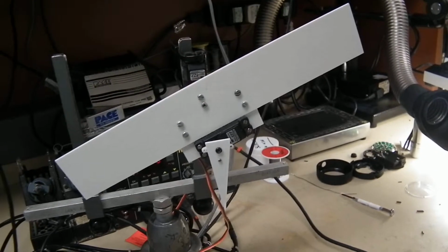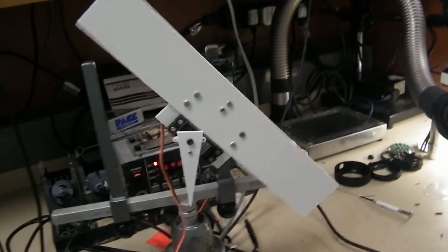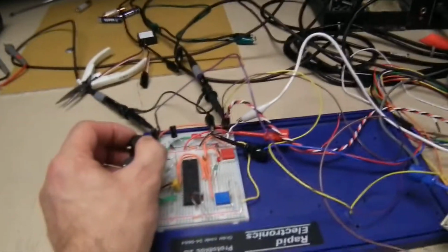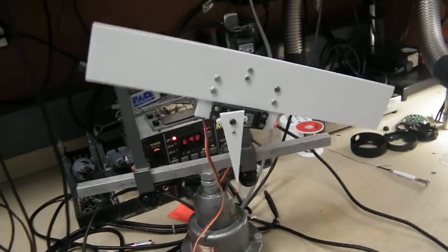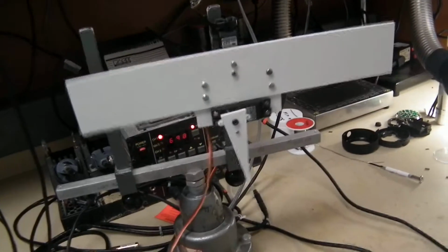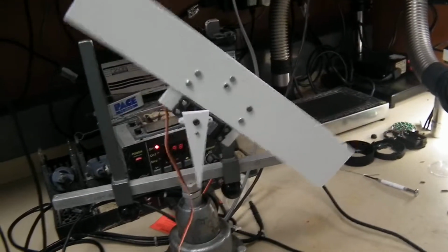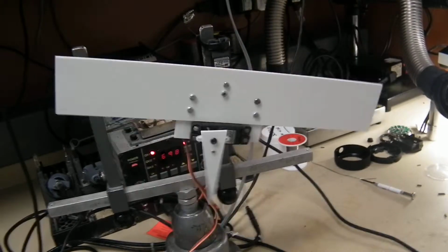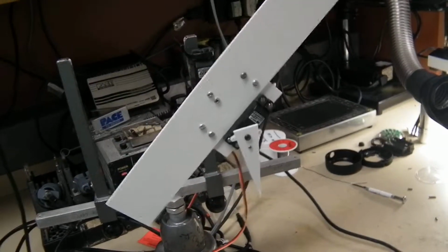The response time with this version of the build isn't quite as good as the previous one. There still is a little bit of shudder. That shudder's down to the resolution that I've set on the generator module. I could actually increase the resolution, so the actual step size of the position is what's causing the shake to the platform. Again, this is an area that can be improved upon. Just demonstrating there is a slight lag if we move it quite fast, the actual settling time is quite slow compared to the previous version.